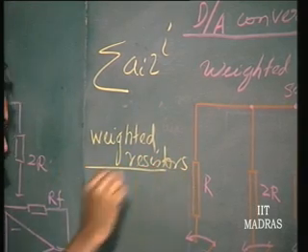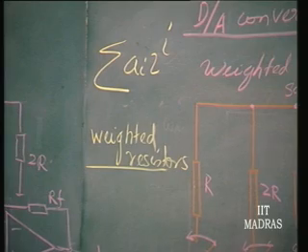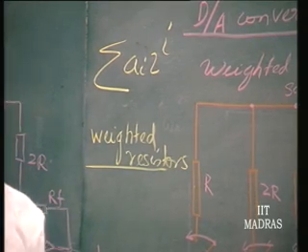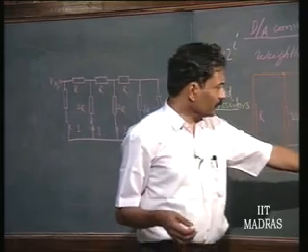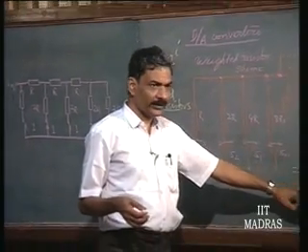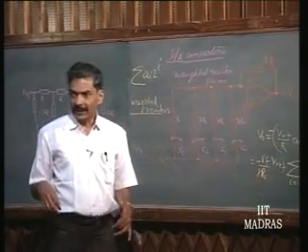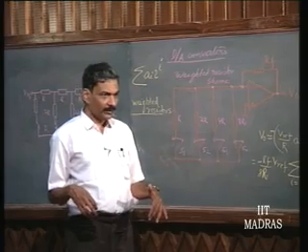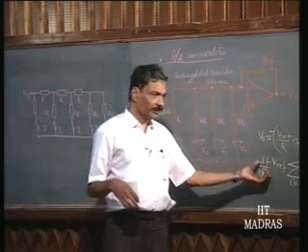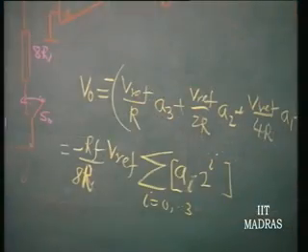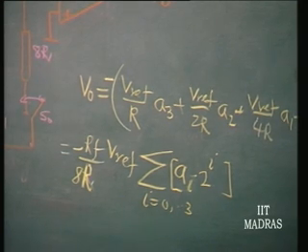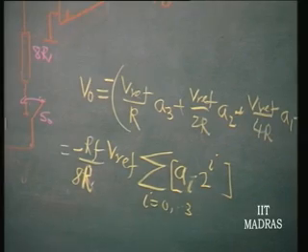It is important that these resistors be precision and temperature independent, since the ratio is coming as a resistor ratio here. It is the ratio that has to be temperature independent, and the tolerance should be good. That means if you want a precision D to A converter, you cannot normally go in for monolithic D to A converters. Have you understood this scheme?